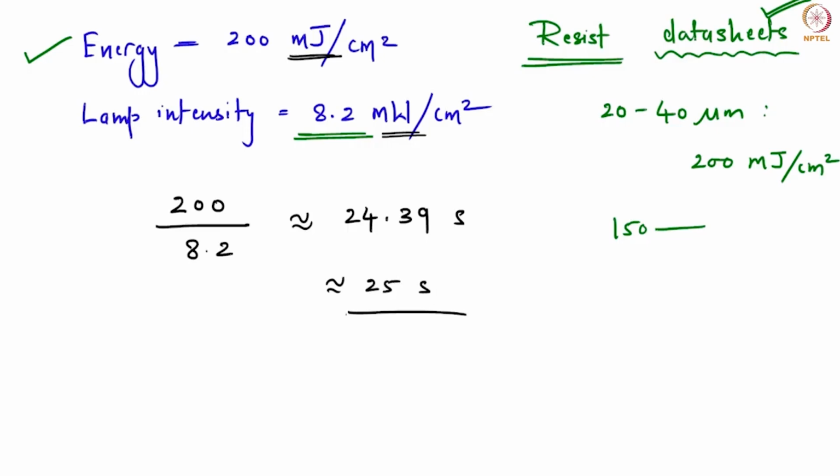Okay. Now here a few more important things which I have not mentioned in the question, but I should tell you. I told you that this experiment is being performed on silicon wafer. So that is also written for a reason, because if you don't have silicon substrate and you have silicon oxide substrate, or let's say you're not making this entire structure on silicon at all and you're making it on a glass or quartz substrate, or there can be other substrates, sapphire substrate, you can choose different, even ceramic substrates for certain applications.